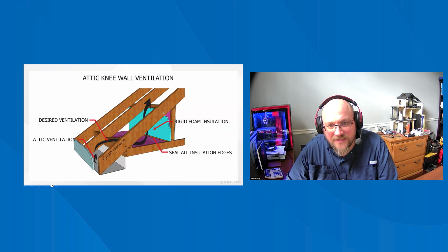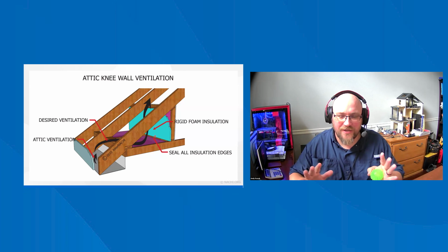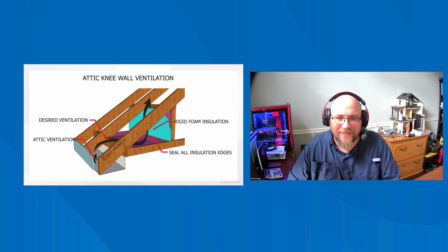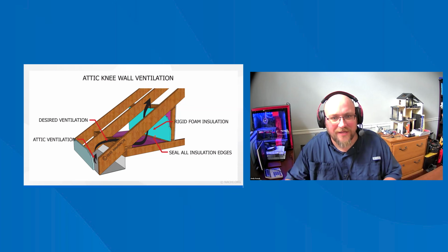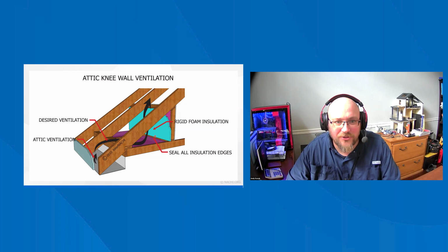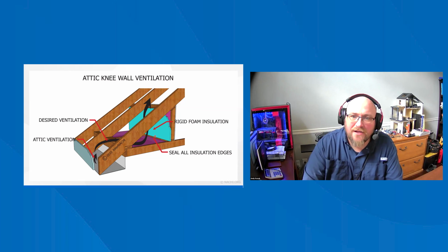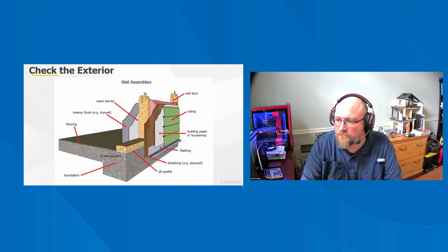But a lot of times you'll find that this bat insulation, if it is bat insulation, has fallen or come loose, or now there's a gap at the top, just because it was so difficult to secure in there that they just kind of threw it up there, out of sight, out of mind, until you're getting in those nooks and crannies with your flashlight and able to see how it's fallen off. So just keep an eye on those areas.